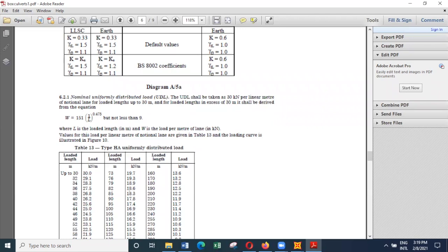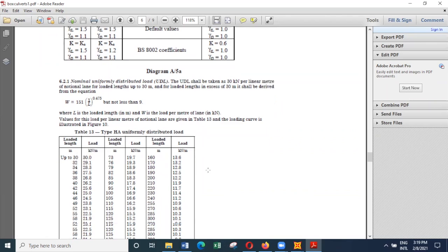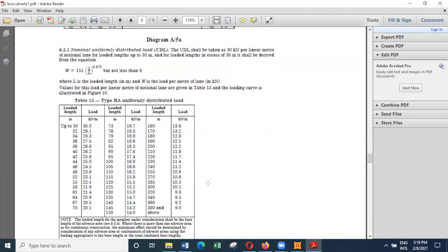So it's a 12-ton, 120 kilonewton load acting across the lane, and only at one location in the lane it will act, and the rest will be the UDL, and the UDL is given per lane. In the earlier British standards they allow the lane width to vary from 2.6 or 2.7 meters to a value like 3.8 meters. In a moment, I'll show you the table.